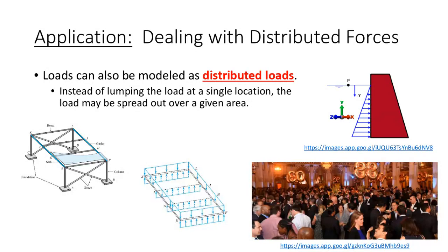So, for instance, let's take the situation with the dam, the one on the top right. What would I need to do? I would need to model this as a linearly distributed load, this triangular load, in order to represent real life.